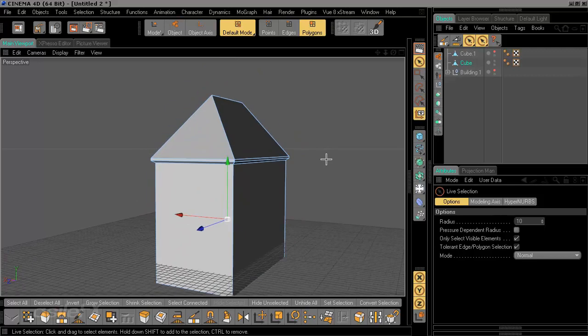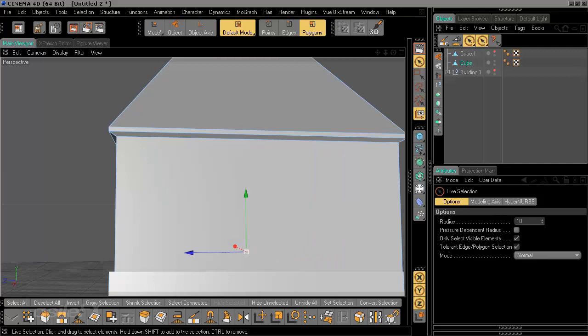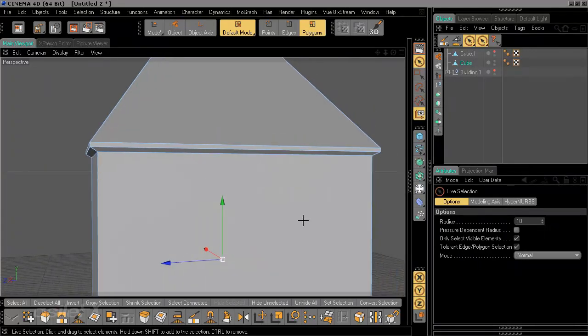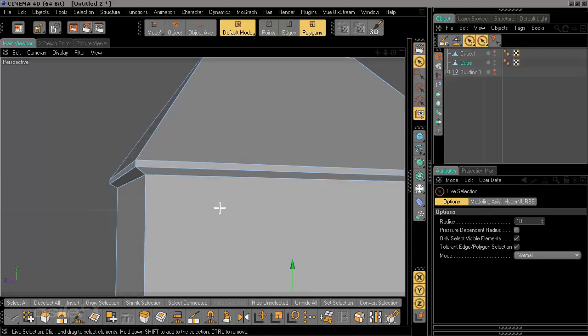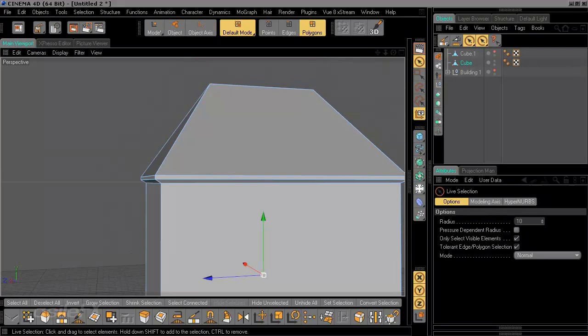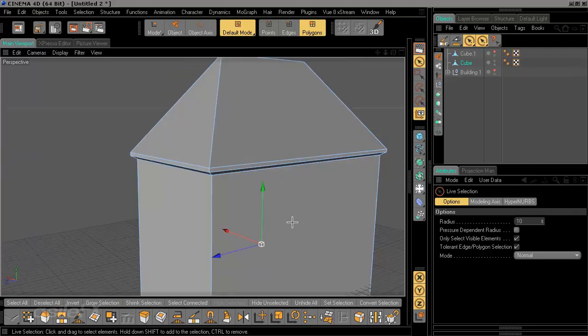So still very low polygon, really just going to be dependent on the normal maps in order to generate the detail. And as I was saying before, if this is way too many polygons, if you're going to have thousands and thousands of copies of this object, you can remove that additional slice and just have basically that lower slice curved up to the top part. And if you want to avoid the flatter 90-degree angles, you can just scale that edge loop.